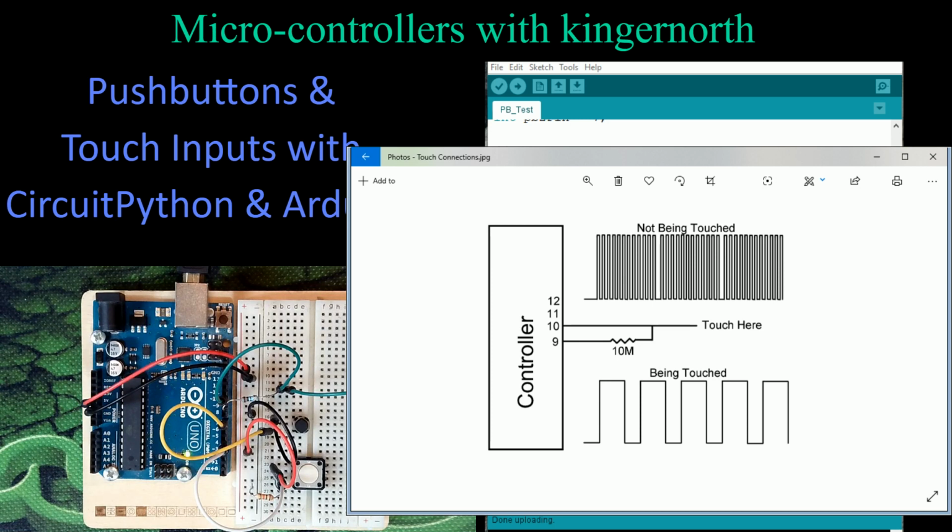When I did a test, I actually hooked this up to my oscilloscope to see what was going on. And the sample file that we're using is the one that I tested. So what happens is, this is happening at about 4.5 kilohertz. So about 4.5 thousand hertz, this thing's pulsing. It pulses a bunch of times, then it takes a little pause, and then it pulses a bunch more times, and it takes a little pause, and then every once in a while it takes a long pause, and then starts the cycle over again.